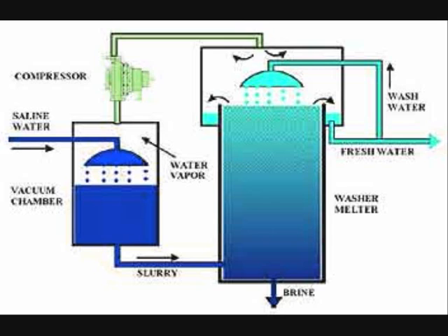Another nice part of freeze desalination is that you can use it with mechanical wind power or mechanical hydropower, because the cooling is done using vacuum cooling, and you can simply use a pump that you drive with hydropower or with some other type of mechanical energy directly, so not involving electricity or the conversion to electricity, to drive the vacuum pump and to cool the water.